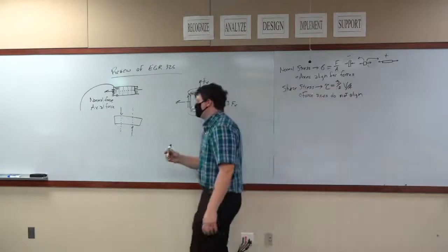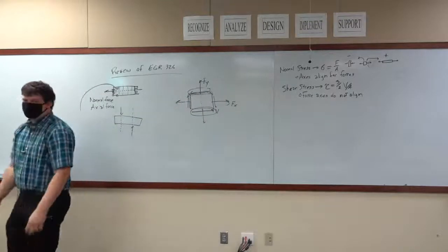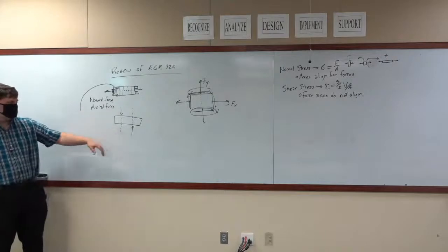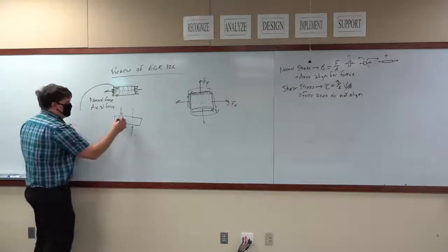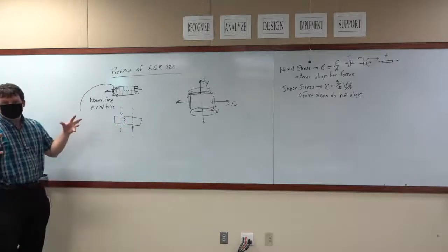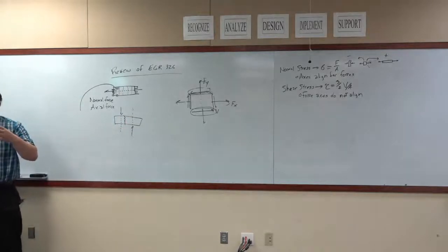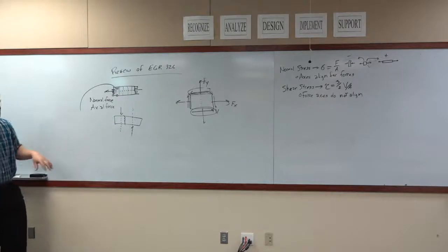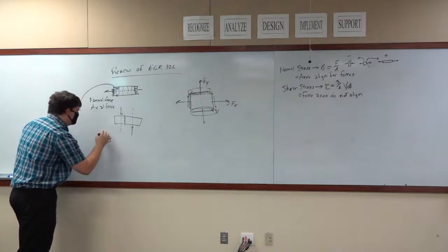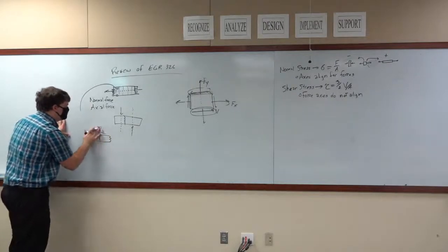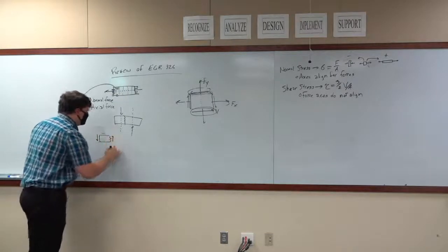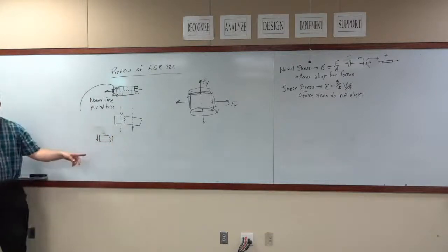Okay? So that's how we know this is a shear force. That's how we know that we are dealing with a shear stress. When this occurs, anytime you were to break this material, pull it apart, and study the total forces being exerted across that cross section, so we just temporarily break it, pull it back together. We're exerting a downward force here, and an upward force is being carried across that cross section.